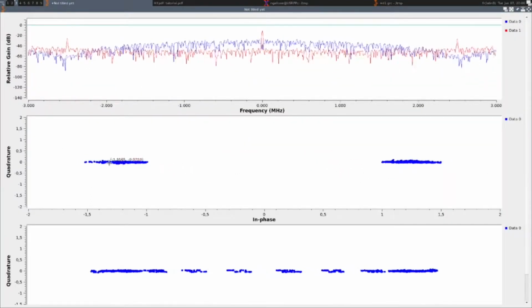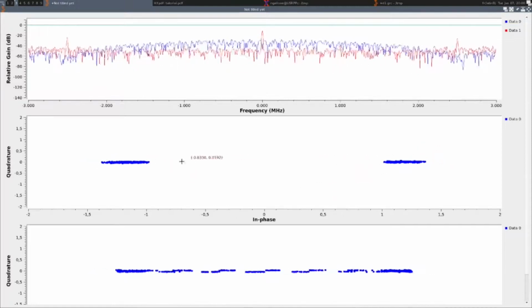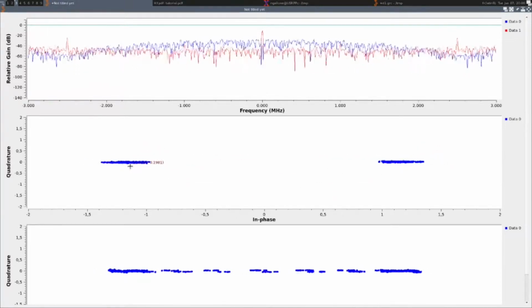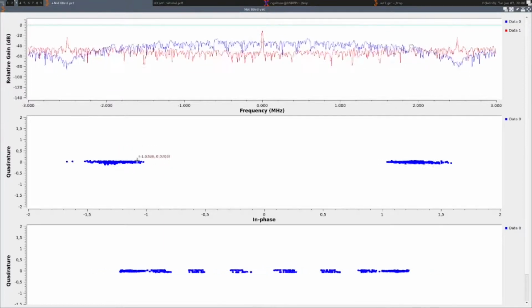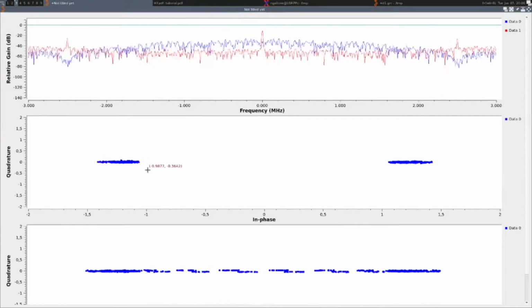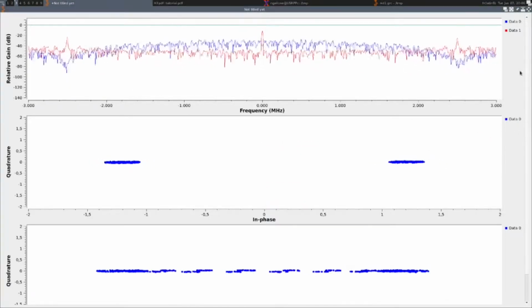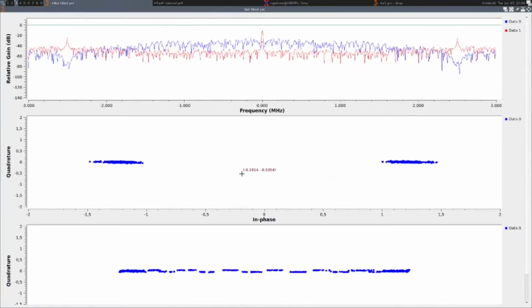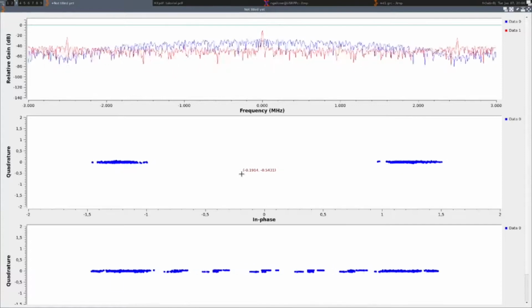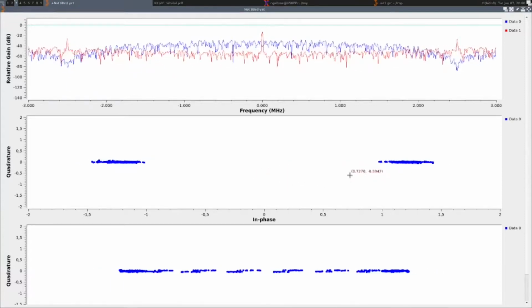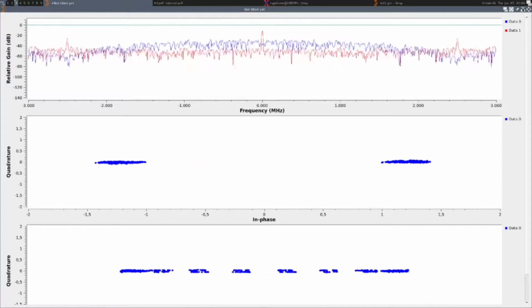And nicely enough, here are the two symbols that are well separated. So now you can go from the soft bit state with fluctuating amplitude to a hard bit with a threshold around 0 here. The imaginary part doesn't carry any information, and all the information is carried on the real part. So here you have the full demodulation with your two bit states.